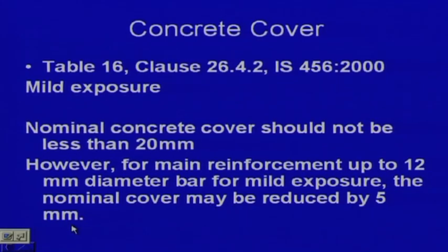That means if it is mild exposure and the bar you are using for slabs is up to 12 millimeter, then we can reduce that 20 millimeter to 15 millimeter. So, for slabs we shall use 15 millimeter. If no other environmental or exposure condition is mentioned, or you are using bar within 12 millimeter, then we shall use this 15 millimeter. Okay.